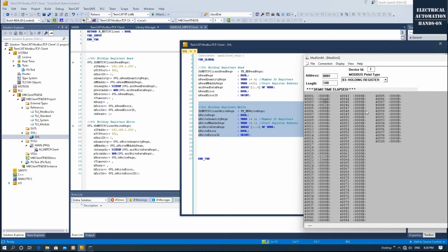Don't forget to test the Modbus TCP. You had better use 2 computers, because it is based on the Ethernet cable, right? So you had better prepare 2 computers, and also check both computers' firewalls and open port 502 for your Modbus TCP communication test.